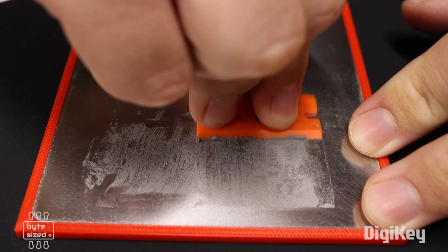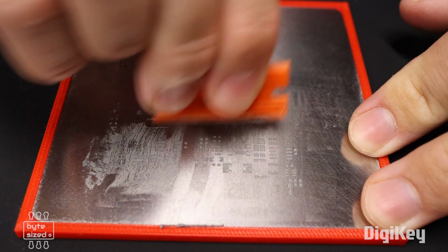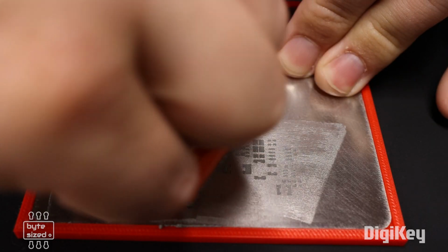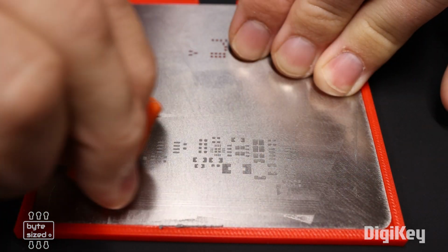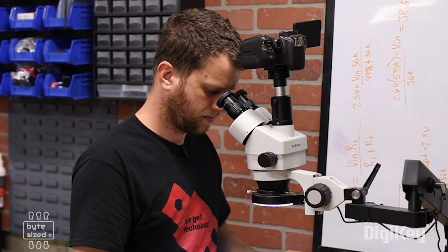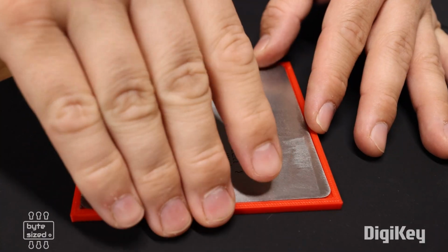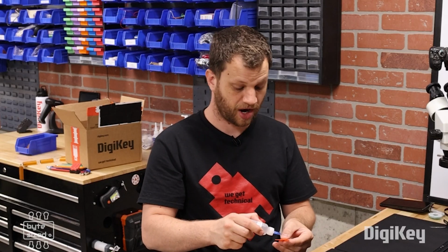I think the proper technique is to get all of the solder paste in one squeegee wipe, but I'm not that good at this, so I'm having to go over it multiple times, cleaning up and filling in spots. Before lifting the stencil up, I look at it under the microscope to make sure that all of the solder pads have plenty of solder paste in them. Honestly, that 3D printed jig worked pretty well, and I'll probably be using that technique in the future.